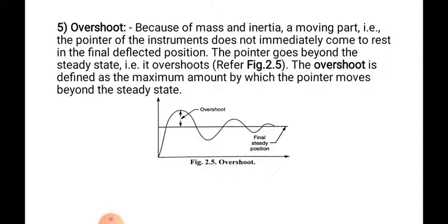Okay, now in this diagram we can see the pointer deflection versus time graph. Okay, in this case, we have stopped giving the input to the instrument, but in whatever analog instrument we have, the pointer gives the deflection after removing the input from the instrument. Okay, and that is nothing but the maximum amount by which the pointer moves beyond the steady state position,